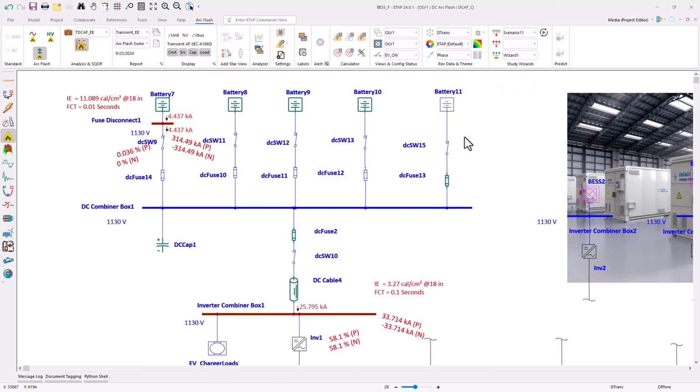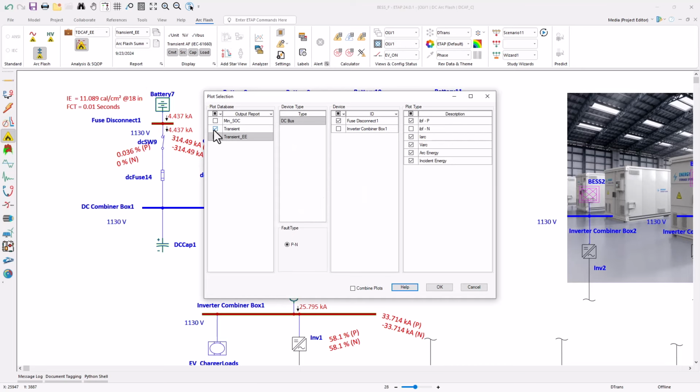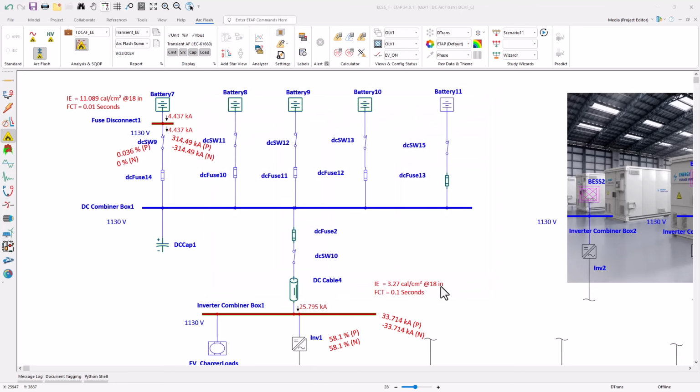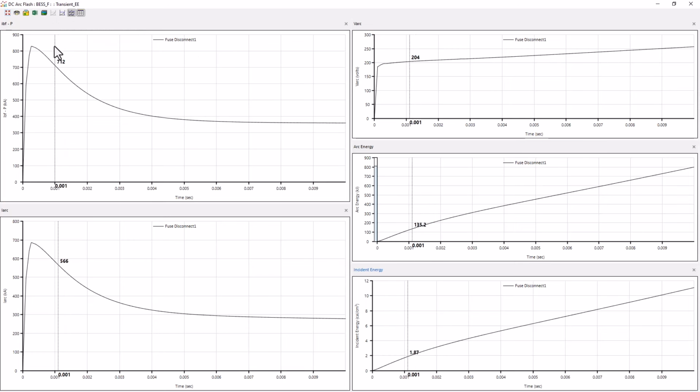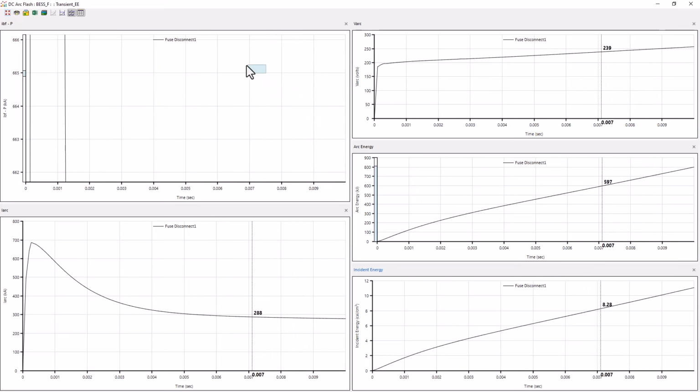As you can see, the combined effect of the arc erosion and elongation would give us a good profile of the incident energy based on the actual physics of the arc and the way the conductors get eroded for a high magnitude of current. So it could also provide us an accurate simulation on how to calculate the incident energy for these sophisticated locations without compromising the conservatism given in the incident energy values.